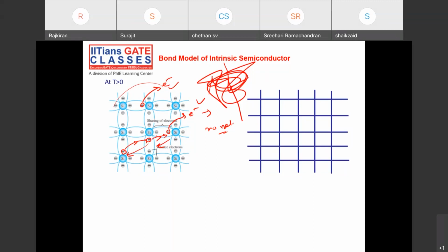Okay, and the hole is nothing but vacancy space. So the vacancy space is also helping you in conduction. It's not the hole helping you; it's the bounded movement, right? The electrons which are bounded are occupying the hole space. So it is the motion of bounded electrons that is helping you in conduction. Instead of telling you bounded electrons, I'm telling you holes. And the holes, if you see, are moving exactly opposite to the bounded electron movement, right or not?